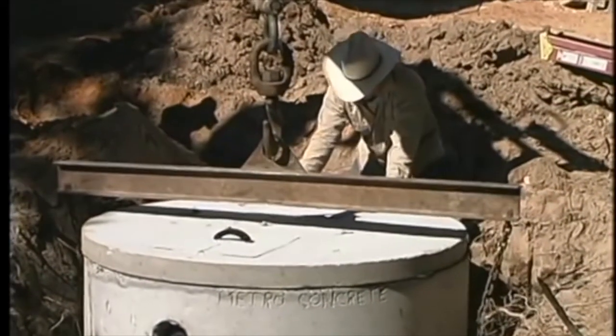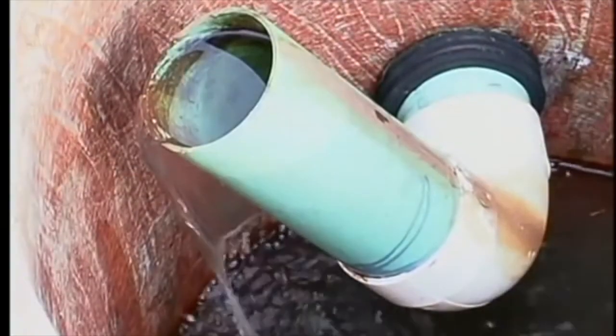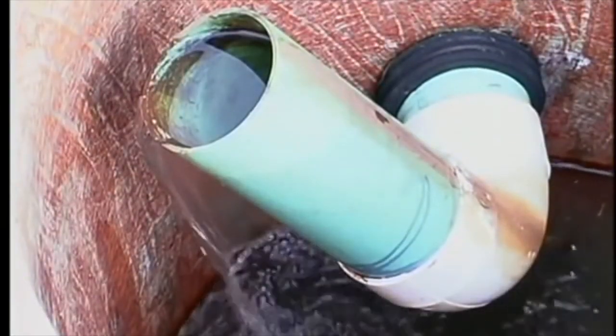Using a septic tank to pre-treat sewage allows secondary treatment systems to work more effectively. The effluent emerging from a septic tank is mild, consistent, flows easily, and is better treated by both aerobic and anaerobic processes.